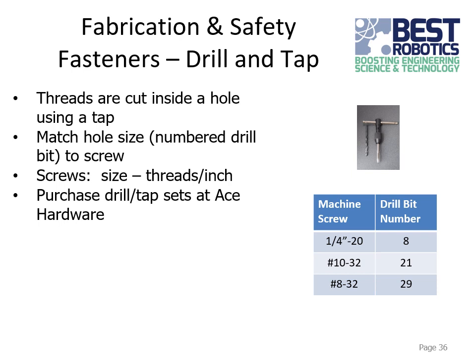Just make sure when you are tapping it, you can see it in that picture on the right, it's a little T-shaped part. A lot of times you'll need to go in a little bit and then back it back out, so that it can remove the bits of metal that are cutting out as it goes along. Otherwise, that metal can fall into the bottom of the hole, or it can get stuck in the cutting surfaces, and then mess up your threads. And sometimes it's good to use cutting fluid on this also to keep the tap cutting surfaces sharp and all that.